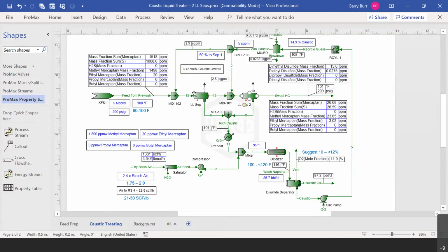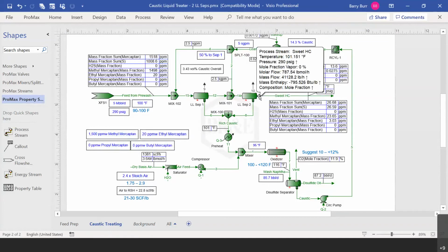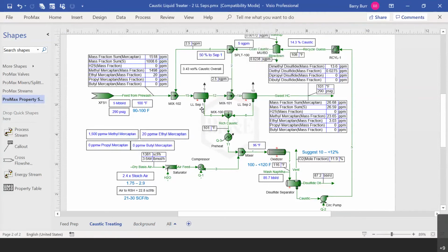The difference, there's some special mass transfer equipment in these, which I assume are designed to make sure that they produce one ideal stage of separation in a smaller vessel than there would have been if you didn't have the special mass transfer devices in them. That's my assumption. I really don't know, but I think there's something in there to help mass transfer that's designed to reduce the size of these separators. And so instead of using a liquid-liquid extraction column that I think has about 7 liquid-liquid extraction trays in a typical column, here you have 2 vessels, and you send part of your caustic to feed the first stage, and then that rich caustic is removed, and then you send part of your caustic to the second stage to treat the residual mercaptans, and that caustic is removed.